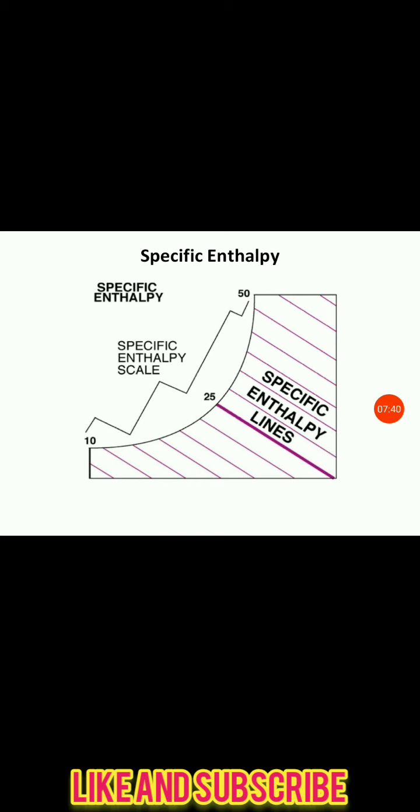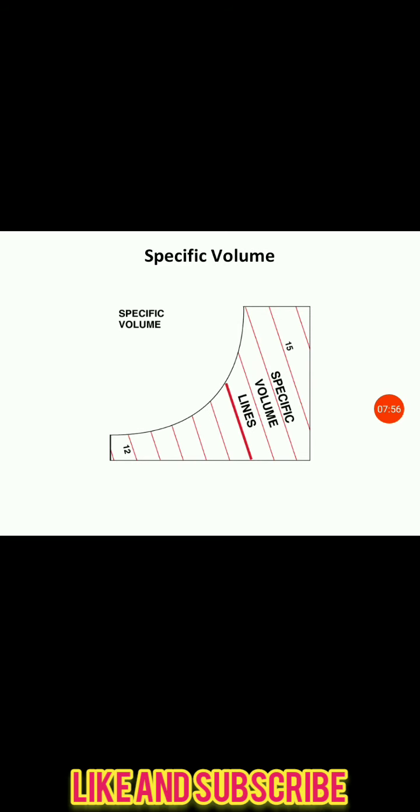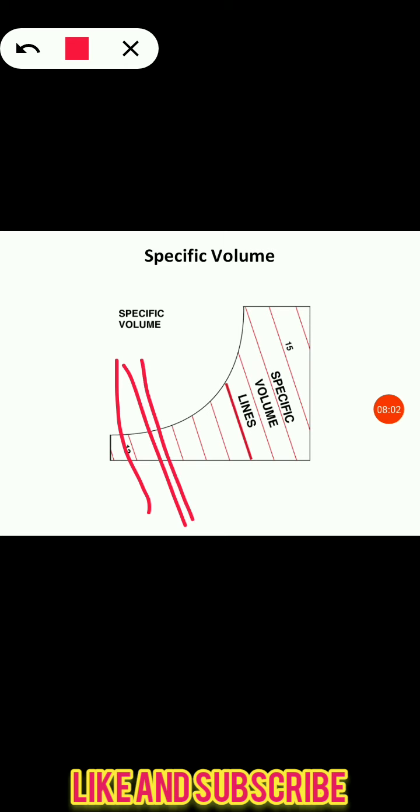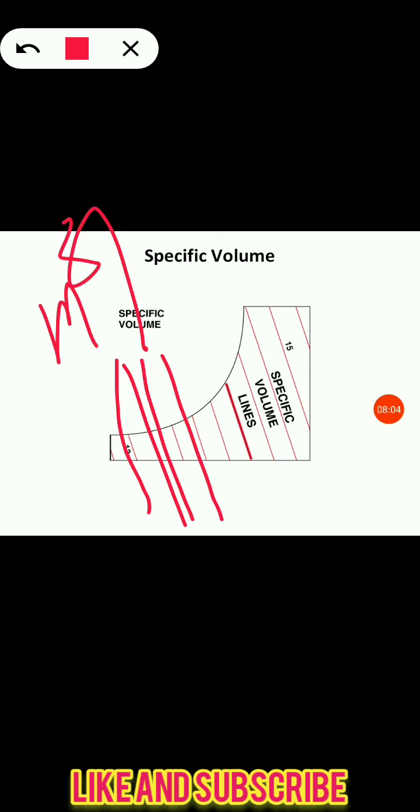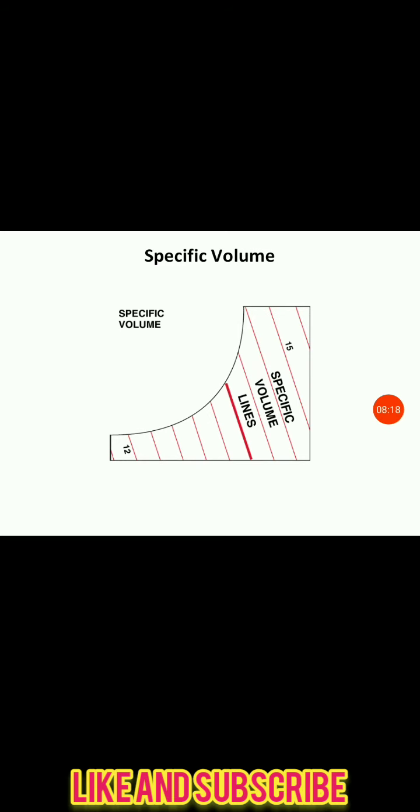We first have to plot a point, then extend that point up to the specific enthalpy scale, and the point where it crosses the scale gives the desired answer for specific enthalpy. Then next is the specific volume line. Specific volume lines are again drawn as inclined lines on a psychrometric chart, and the unit is meter cube per kg of dry air. On your screen you can see the specific volume lines.